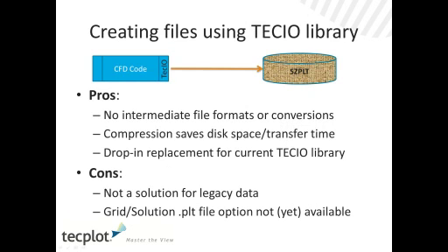This does bring up a question that I think I'll probably talk about more later, in that the most natural way to output that in Tecplot land would be to output one grid file and then multiple solution files, which really is quite analogous to the Fluent case and data files. We don't have that implemented with SZL data files yet, so you will be creating one file that contains all the time steps today, but we'll work on that later. And it will take advantage of sharing, right, if it's a common grid. So it won't necessarily be duplicating the grid, but it is required to be in one file.